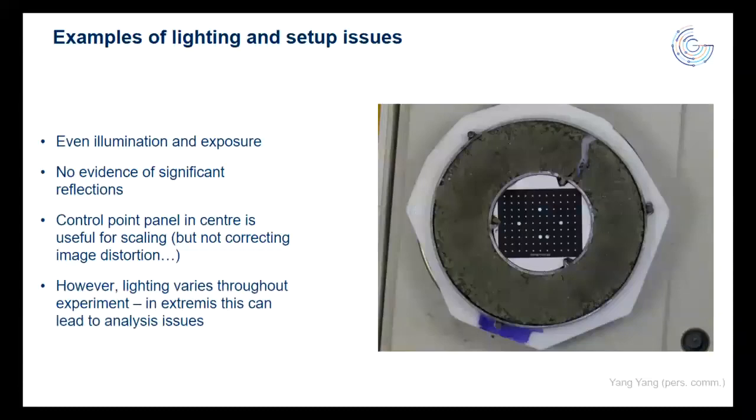The downside is this is in a lab environment relying somewhat on ambient light. So throughout the day, the ambient light is changing, okay? Now, the algorithm that we use in GeoPIV-RG can account for this to some degree. It's semi-invariant to the ambient overall light intensity in the image, but it's not perfect. And this was really, really quite challenging, even in spite of using that zero normalized cross-correlation algorithm. So shroud the sample, use artificial light, control it at all times would be my takeaway from that one.